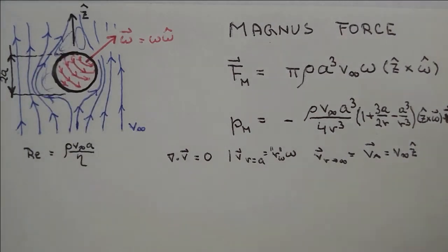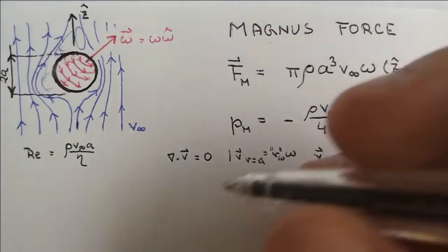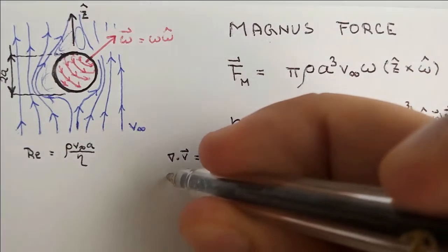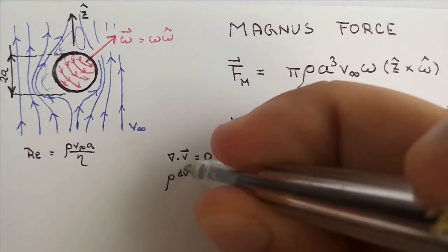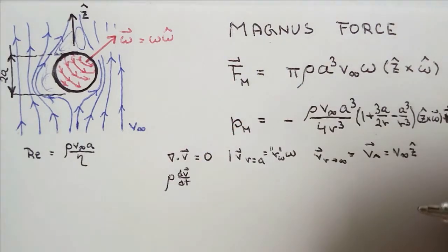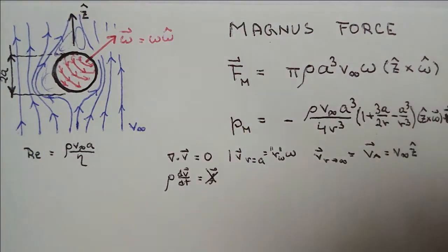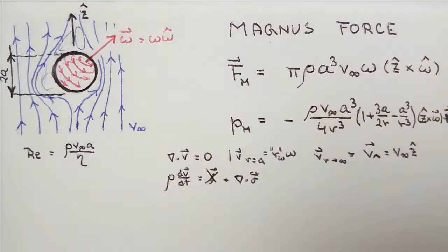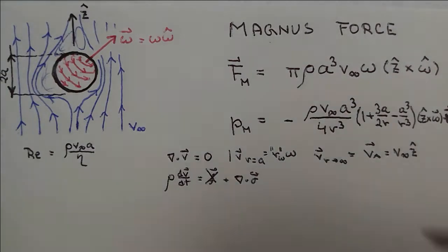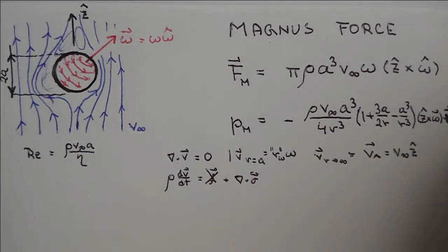So the second equation is basically the Navier-Stokes equation, but I will derive it anyway, because let us write the equation of motion of the fluid. Mass times acceleration is equal to force. There are no body forces in this coordinate frame, plus the divergence of the surface forces, which come from the stress tensor.